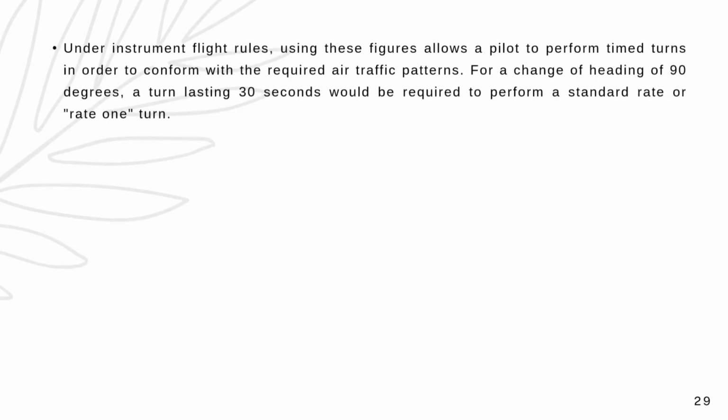Under instrument flight rules, using these figures allows a pilot to perform timed turns in order to conform with the required air traffic pattern. For a change of heading of 90 degrees, a turn lasting 30 seconds would be required to perform a standard rate or rate 1 turn.